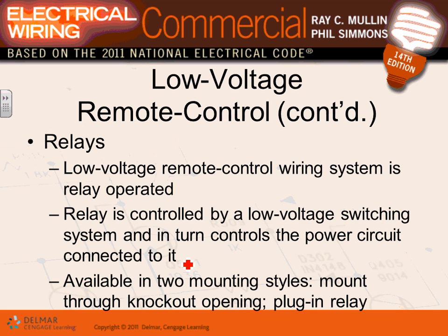The relay, guys, is the link between the low voltage switches and the high voltage lighting fixture. You'll see in a second, it's operated by low voltage, my term low voltage wiring system. So you're looking at 24 volt to operate the coil of the relay. So the switch is turning the power. Instead of turning the light on and off directly from a line voltage switch, you turn the relay on and off, and the relay will turn the light on and off. So that's the whole idea of a relay.